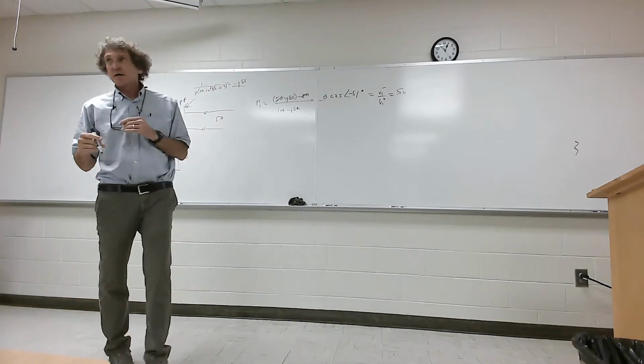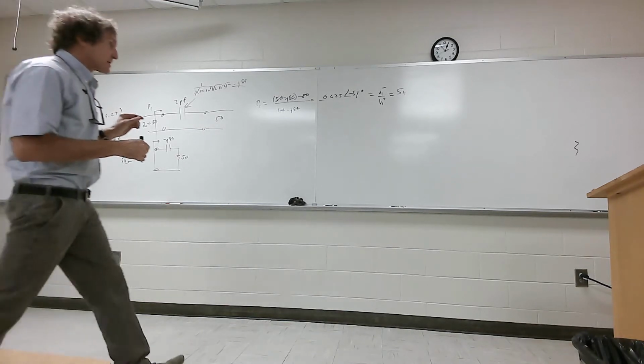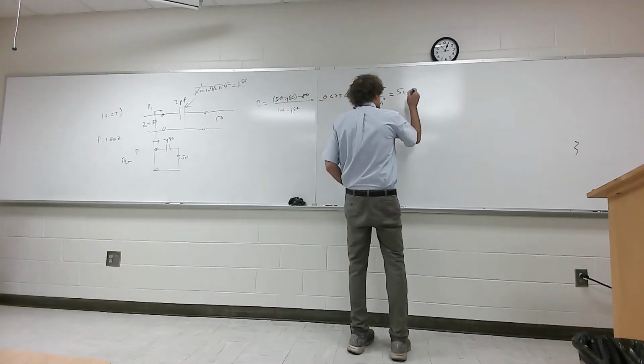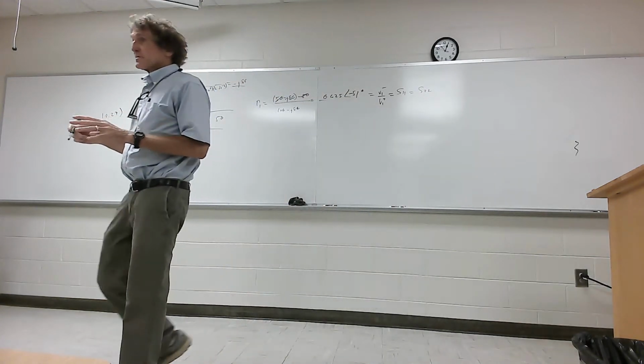That's S11. Can anybody tell me what S22 is just by observation? Isn't S11 the same as S22 because it's a reciprocal network? Doesn't that network look the same forward and back, class? Y'all hear me on this one? So you don't even need to do a calculation on S22. This is S22. Now, y'all agree with this, first of all.